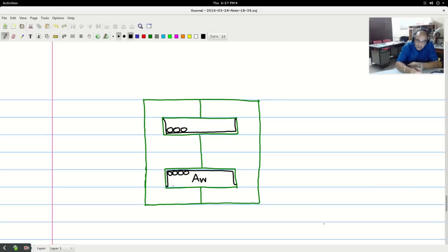You will notice that when you are placing two conductors, there will be gaps here. These are not filled. So this is also loss of some of the area. And if you are having multiple windings, primary, secondary 1, secondary 2, so on, every layer is separated by insulation layer. Then you will have another secondary, and if you are having multiple secondaries, you will have one more layer of insulation, and this also will eat up into the available window area.